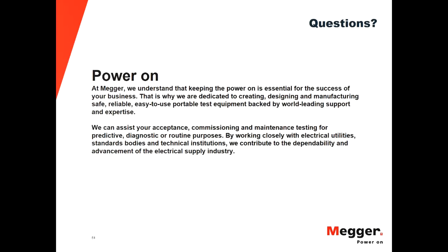Capacity testing, on the other hand, gives you an idea of the true capacity of the battery, right? So you are actually drawing current from the battery, which is ultimately the objective of the battery. The battery is supposed to provide power to the loads in the case of an outage. So you are simulating an outage. You are drawing a certain current from the battery, and you're observing whether the battery will be able to provide a sustained power to the load for the duration that it's supposed to. So capacity testing is of higher value as compared to impedance testing, but in a good maintenance program, you can have both tests complementing each other.